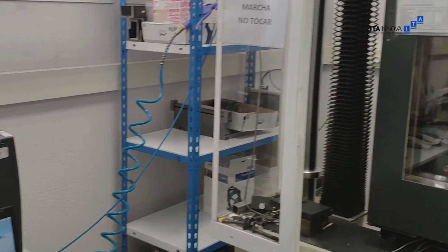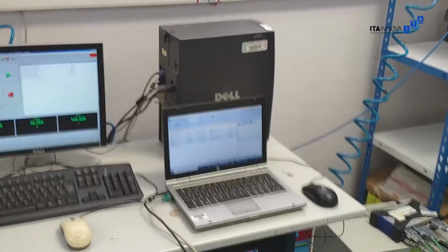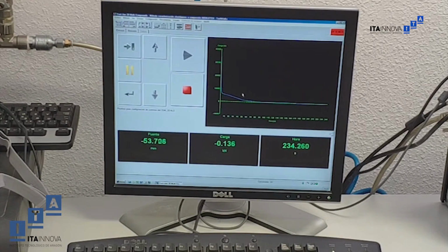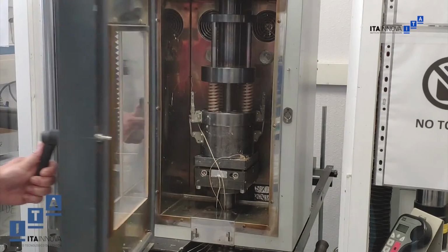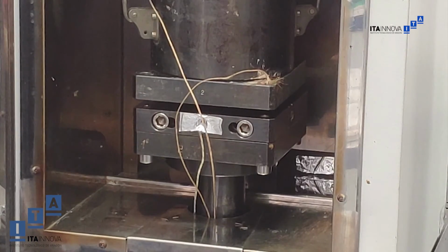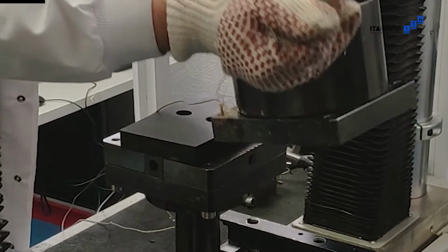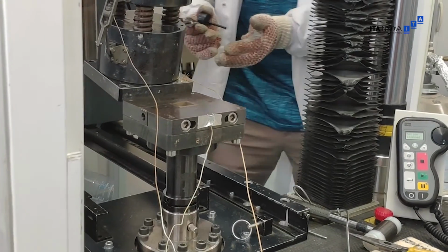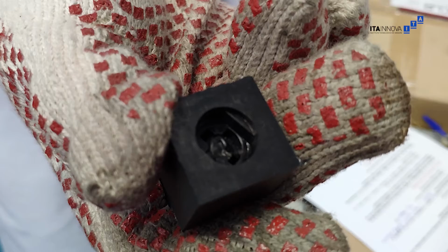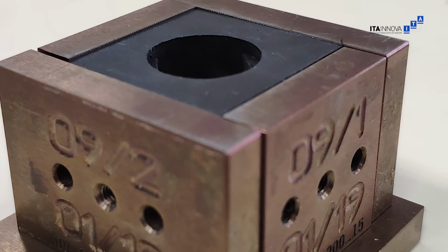During the procedure, the material is transferred from the transference chamber to the mold cavity through a transference piston. Finally, the rubber sample is extracted from the mold and the demolding force, which corresponds to its specific microtexture and rubber compound, is measured.